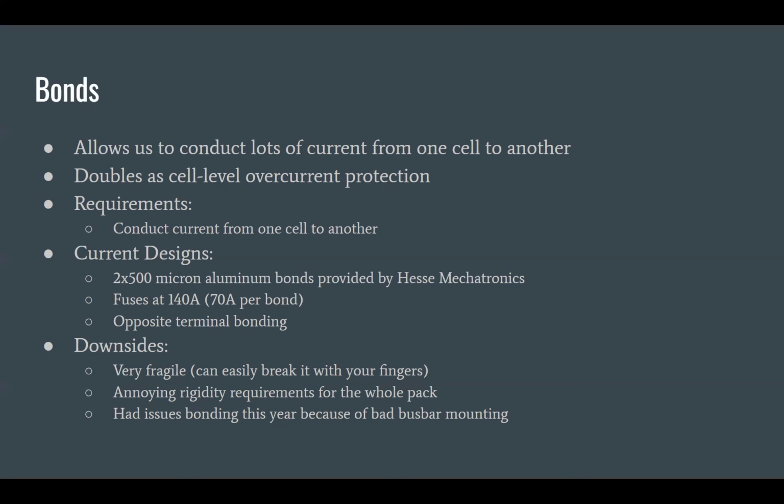But yeah, the idea is that they do spray our battery pack at competition, and we want to make sure that no water can directly get in. There's a rule, I think it's called out in tech, that you shouldn't be able to poke any battery cells with a stick. The motivation is to make sure you don't have the wall of your battery pack with an air hole and then you can just see the cell. And so that's why we have those offset walls, to make sure that it avoids high pressure jets of water, but it also avoids the stick test.